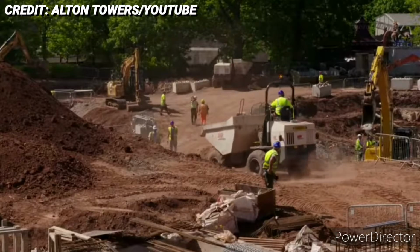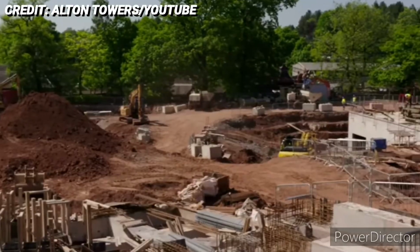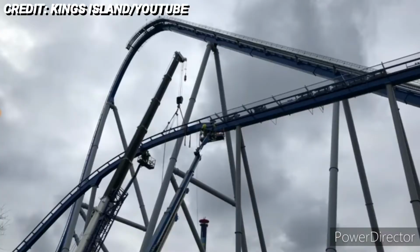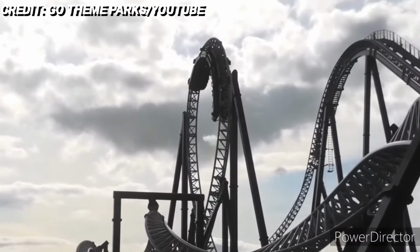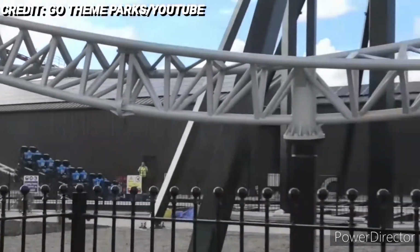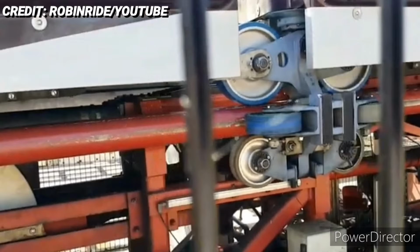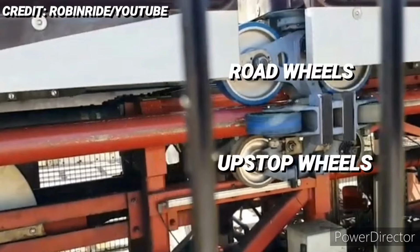The vertical construction of a roller coaster itself can take roughly 9 months to a year, depending on the scale of the ride. Once vertical construction is fully completed, the ride vehicle can be inserted onto the track. The trains for a roller coaster consist of a set of wheels that are very different than the wheels found on that of a locomotive train or a car. All modern roller coaster trains have two wheels on top of, underneath, and on the side of both rails of the track, preventing the train from coming off the track in any direction.